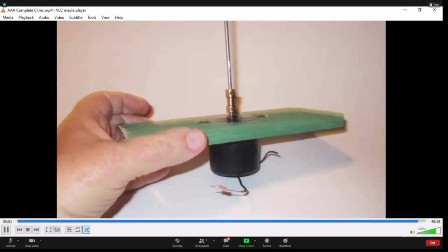After I clumsily broke off the plastic axle on the carousel, I used a 1/8 inch steel rod to replace it. I connected the new carousel axle and the Hankscraft motor with a coupler I found on Amazon and secured it to the motor and carousel rod with the set screws on the coupler.